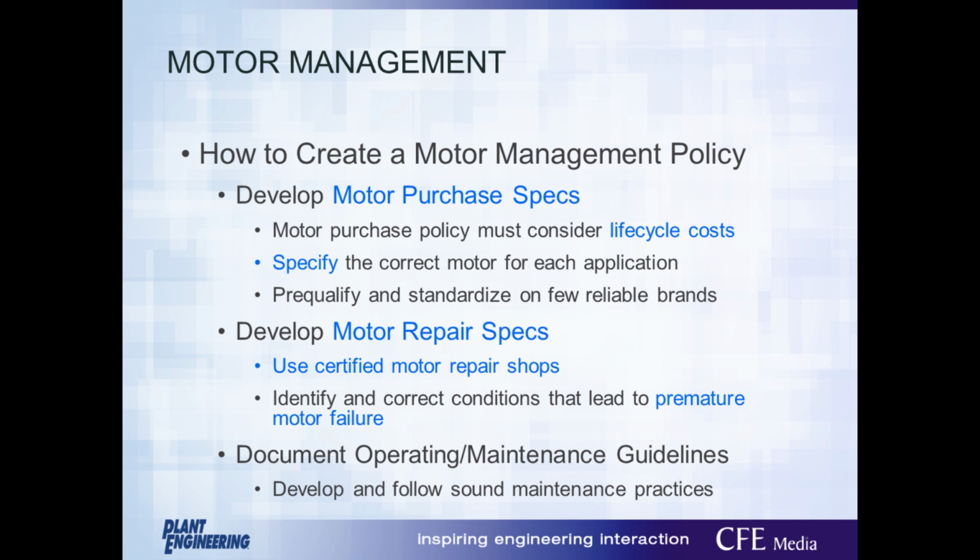And also, just like for purchasing, develop motor repair specifications. If you're using a certified shop, they can likely help you create a repair specification. Honestly, if they won't help you do that, you might want to find a different shop.